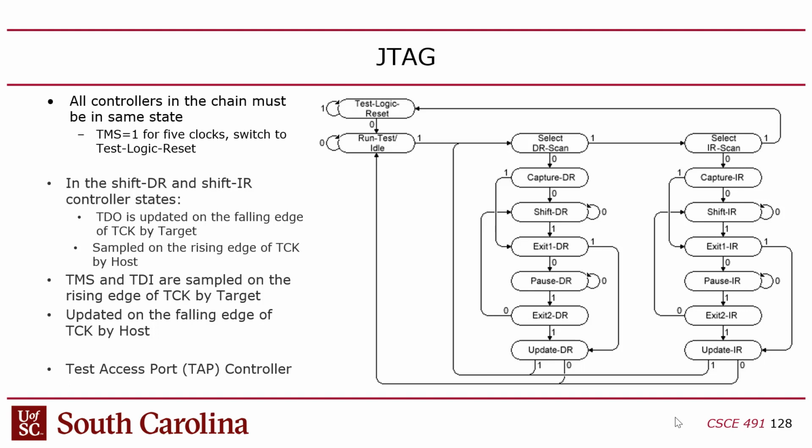But this JTAG, the way I'm presenting it, is assuming you've got just a direct JTAG connection. And people still do that. Usually with this, there's a little tiny ribbon cable with like six wires. You plug that in and you can get JTAG control. But of course, you can also run it on top of USB, which is how you do it for phones. Like if you're doing the Android debugger for an Android phone, and I think iOS probably does it the same way. I've never done it with iOS, but and then of course the FPGAs.